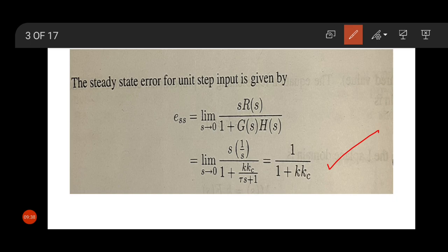For the first order and second order system, the roots of the closed loop system with proportional controller lie in the left half of the s-plane, irrespective of Kc, and the system is completely stable. But this is not the case for higher order systems. As Kc increases, some of the roots of the characteristic equation may move towards the right hand side of the s-plane and drive the system to instability.